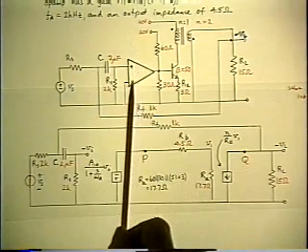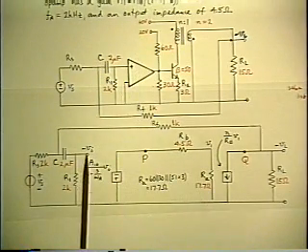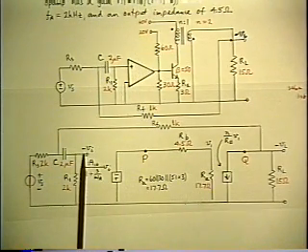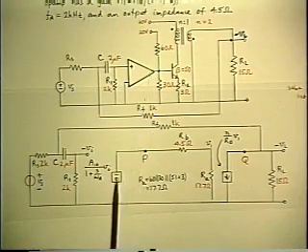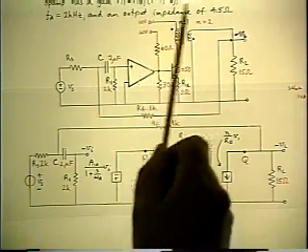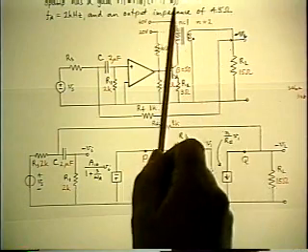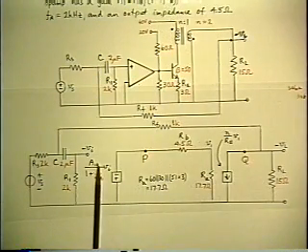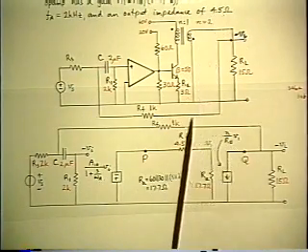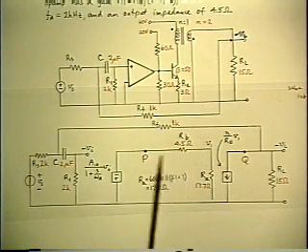Likewise, all you need to represent the driver stage is infinite input impedance with the voltage VI, and represent the output by a Thevenin generator described by the specification, which is a flat gain of 8 dB, a pole at 2 kilohertz, and an output impedance of 4.5 ohms, which is the RB.